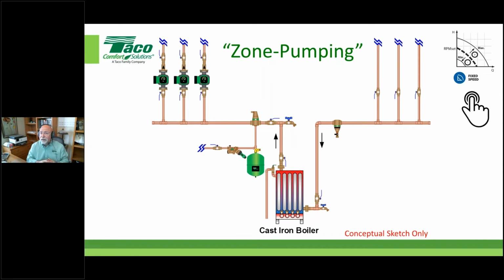So its input is never going to get a signal to speed up or slow down. So understand there's been a bunch of automatic modes used in this application that are not doing a darn thing. Again, if the circulator doesn't get the input to make a decision to make a change, it's never going to change. It just goes to a factory preset RPM when it starts up, and it'll just sit there and work accordingly. So there are plenty of pumps installed right now where people think they're automatically doing things and they're not. Okay, so anyway, these are things to understand.